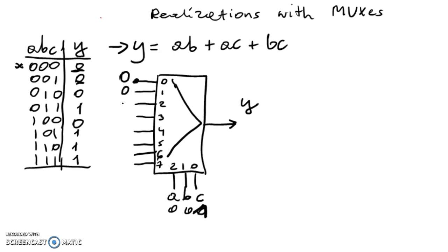So you simply copy the truth table values into the appropriate inputs of the multiplexer, and earlier you connect the variables, the inputs, to the select lines of the multiplexer. It is the simplest solution. And now you have implemented the majority of ones detector, or cout, using a single multiplexer and no more elements.